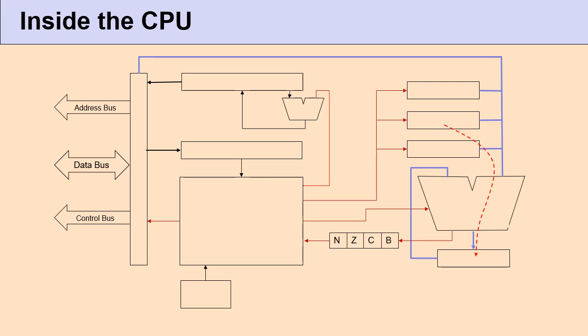The next instruction, when I say add A comma B, register B will be enabled to one of the ALU inputs. The accumulator A is already available at the other input of the ALU, holding the previous value of register C, and then the add signal will add these two numbers and send the result back to register A. So if I want to put that result back in memory, for example, I have to route it from register A to the memory through a separate third instruction.